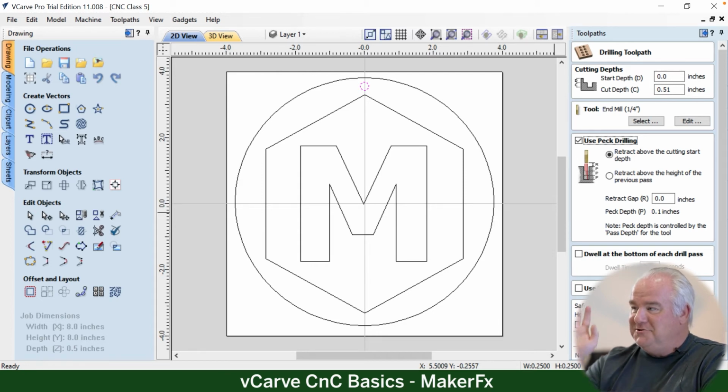I speak from personal experience. In order to place the MDF that represents the spoil board today, I needed to drill some 1/4-inch holes so I could get some bolts to go through into the T-track. So I had measured, and this was 3/4-inch MDF. I didn't do pecking, and I just wanted it to drill. And it started, and all of a sudden it started to smoke. I mean, there was smoke coming out of this, and I hit the E-stop of the machine.